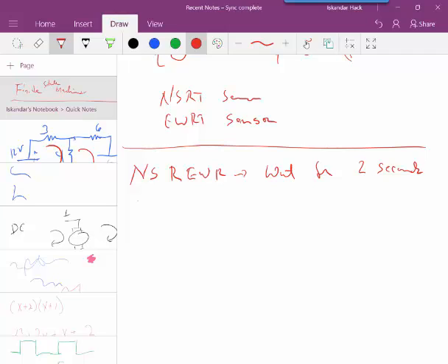Then our next state is going to be a north-south. Right now, for our first example, I'm going to ignore these sensors and not worry about people turning right. I'm just going to do a normal 4-way stoplight with just a few states. North-south green, east-west red, and we're going to wait here for 30 seconds. In other words, traffic going north and south has 30 seconds,